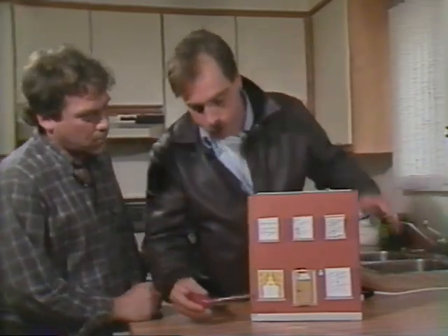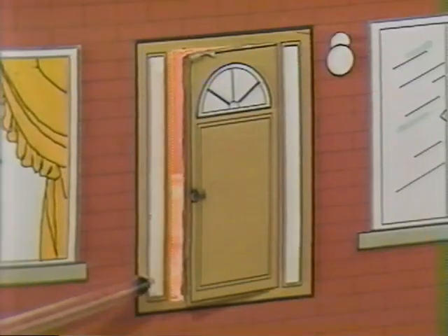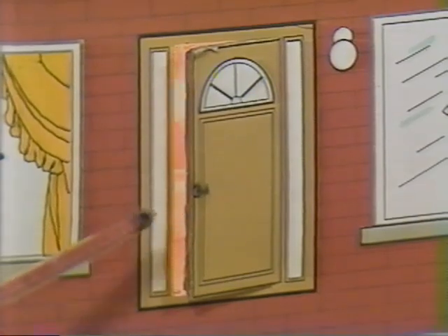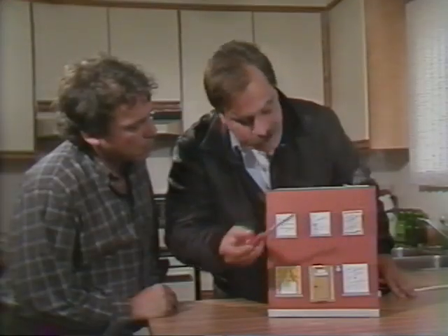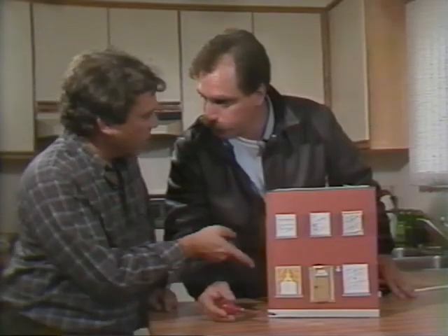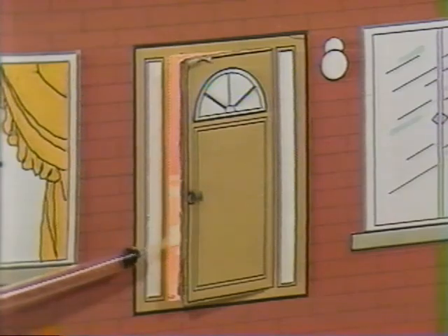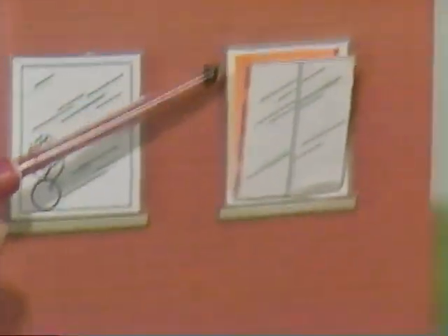And what I want to show you with this model is that smoke put to the doors or openings on the box on the main floor actually enter the building, while smoke put at openings on the upper portion of the box exit the building. The driving force is the light bulb you've got in the box. That's correct. We've got infiltration taking place here. We've got exfiltration taking place here. And each of these things has a different effect on the house.